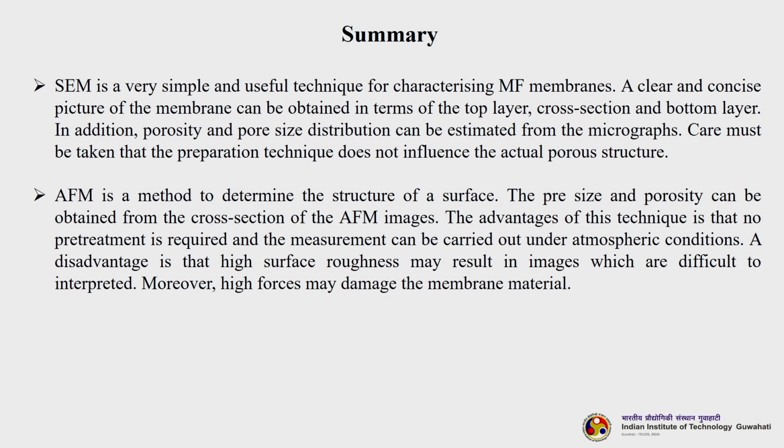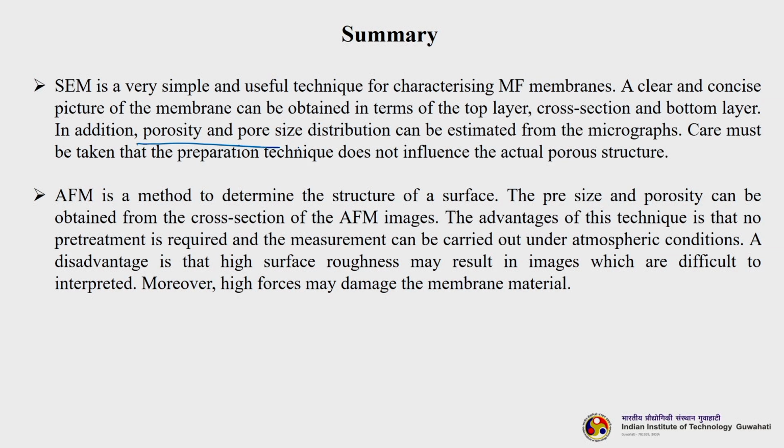Let us wind up today's class. In summary, SEM is a very simple and useful technique for characterizing microfiltration membranes. A clear and concise picture of the membrane can be obtained in terms of top layer, cross section and bottom layer. In addition, we can find out porosity and pore size distribution. Care must be taken in the preparation of the sample.